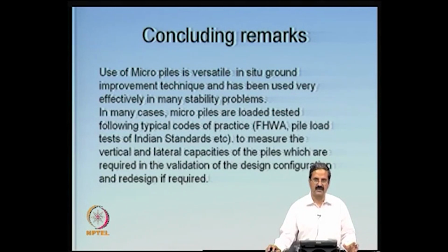What I suggested to them was to do a proper lateral load test. For example, one can do a lateral load test for 10 meters, 15 meters or 20 meters, install 3 piles, and then calculate the actual lateral load capacity of each pile. As you have seen, there are some assumptions in the theory, like the bond capacity, and they are all rough estimates. So, it is better to get the numbers from the field and take that number.